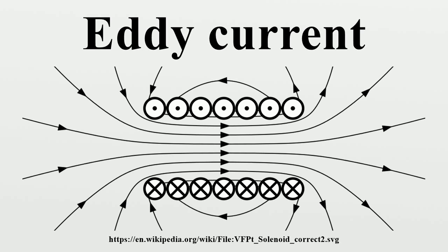Explanation. A magnet induces circular currents in a metal sheet moving past it. See the diagram at right. It shows a metal sheet moving to the right under a stationary magnet. The magnetic field of the magnet's north pole N passes down through the sheet. Since the metal is moving, the magnetic flux through the sheet is changing. At the part of the sheet under the leading edge of the magnet, the magnetic field through the sheet is increasing as it gets nearer the magnet.